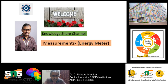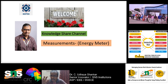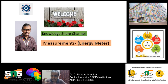Energy is nothing but the total power consumed by any equipment for a specific period of time. You know the difference between power and energy. Power is nothing but voltage into current. Voltage into current into time is your energy. So, power into time is your energy. Please understand, how much time this power has been given to a particular load is called energy.